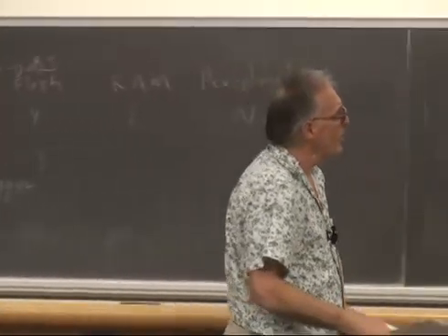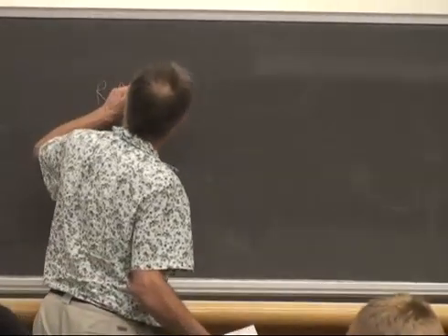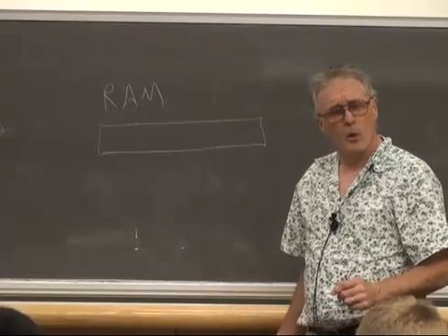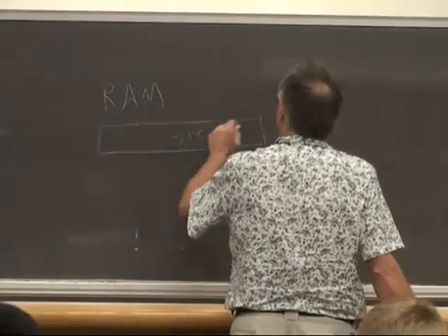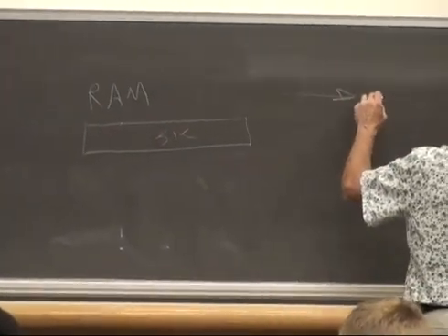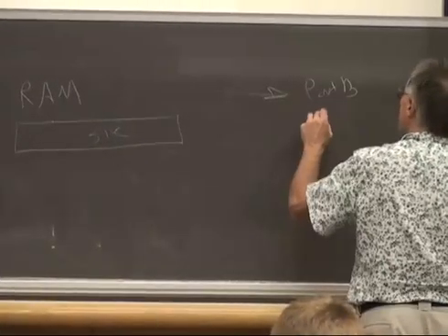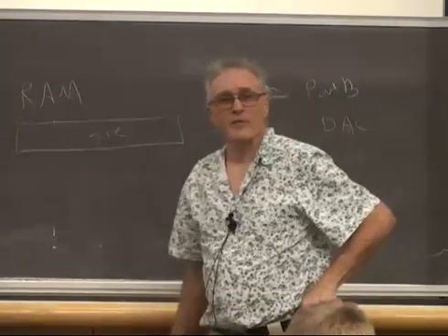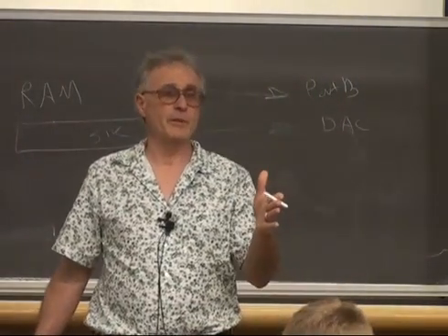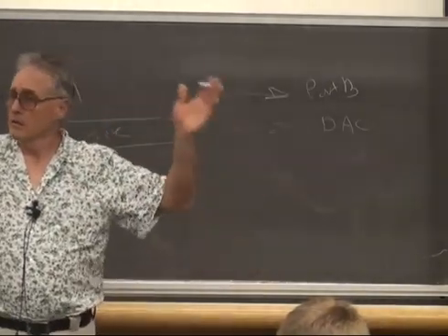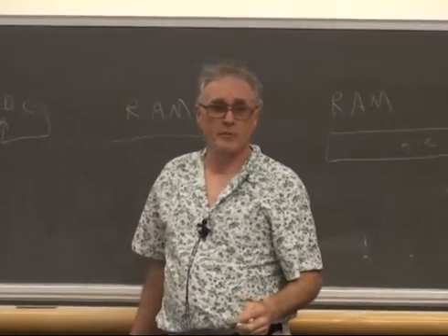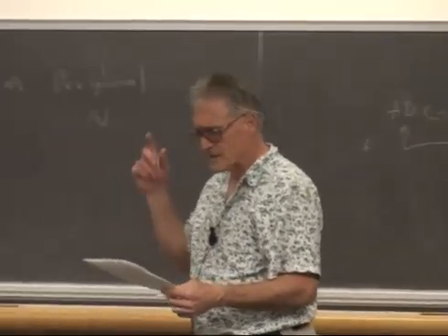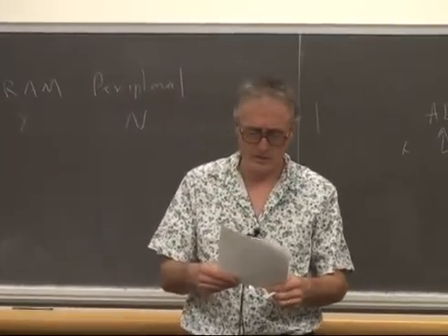Oh, what would you use that for? Well, let's say that you were targeting RAM on one side, a big block of RAM, which happened to be, say, a sine wave table. And the other end, you were targeting port B, to which you've hooked this parallel DAC. Then you'll produce a sine wave forever with no CPU involvement. It'll just sit there and produce a sine wave forever if you put it in repeat mode. So you have one shot and repeat mode. As I said, you can auto increment source and destination addresses.